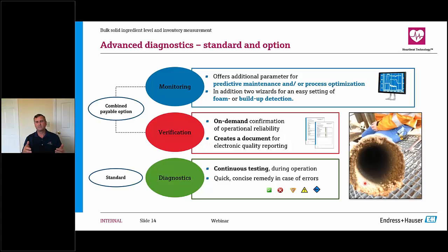And that's what some of these advanced diagnostics today allow us to do. It allows us to continuously look at that build-up and say, okay, is this unit still working the way that it's supposed to? And we can also run intermediate or unscheduled verification protocols to say, here's how it worked the day it was produced and installed. Is this device still running exactly the way that it did that day? So then we can say, has anything changed? If everything is good, we're good to go. If we get some warnings, then maintenance can get involved and see what may need to be done. It might be a thing like cleaning the antenna, for example.